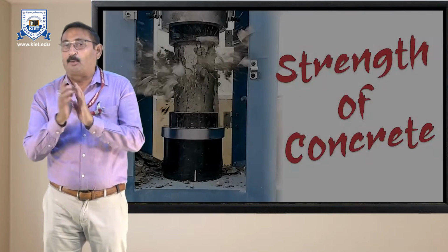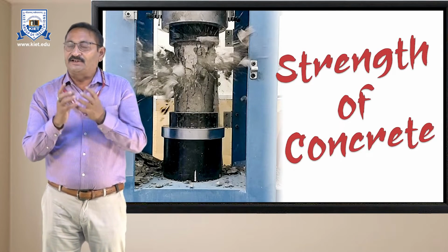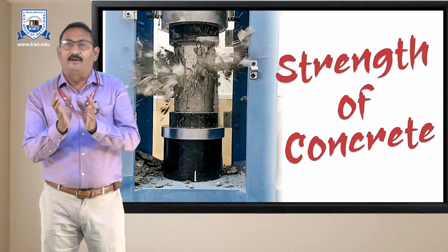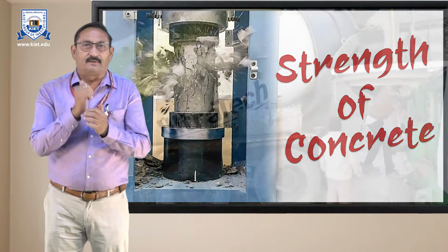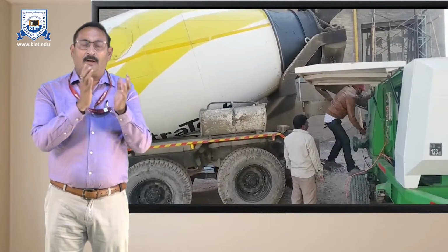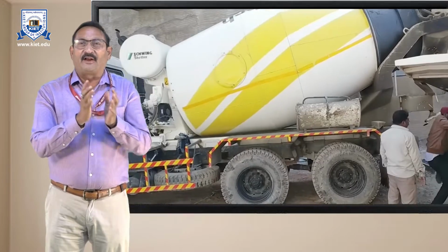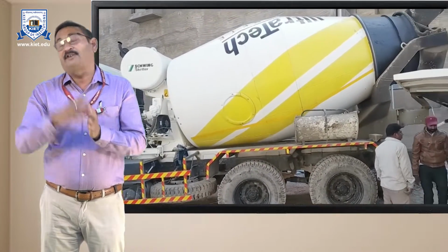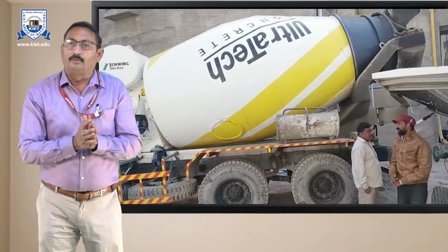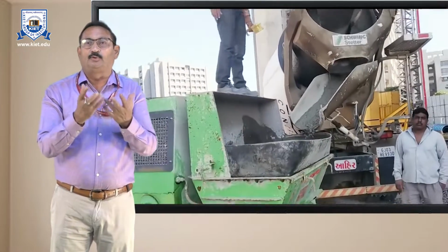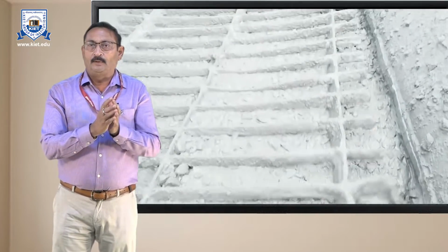Now, the second main important thing is strength. The strength of concrete is limited by the strength of the paste, since material, that is mineral aggregate, with rare exceptions, is far stronger than the paste compound. That is why it is more important to check the paste.